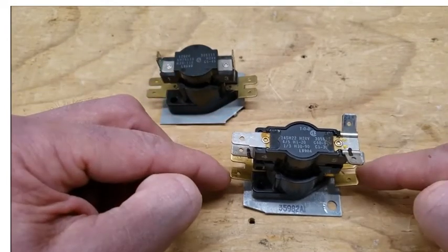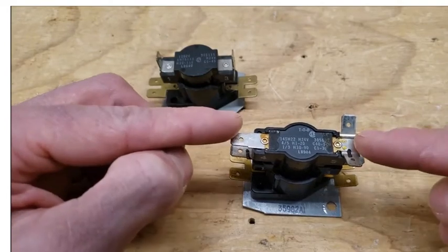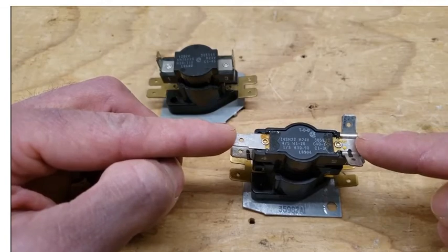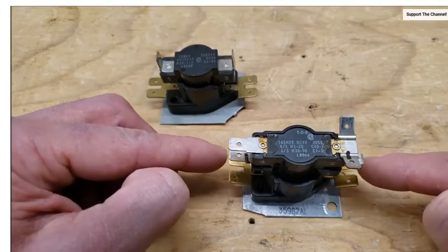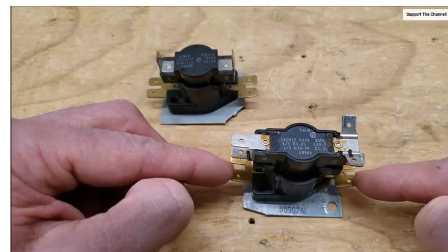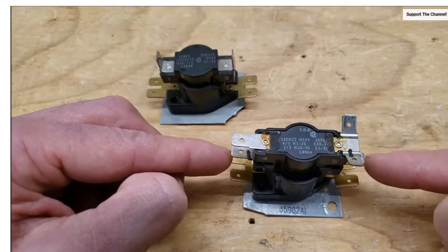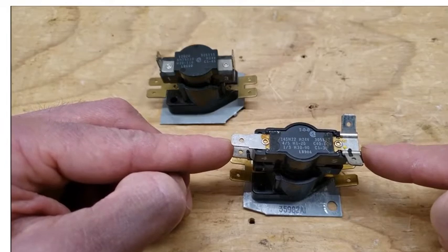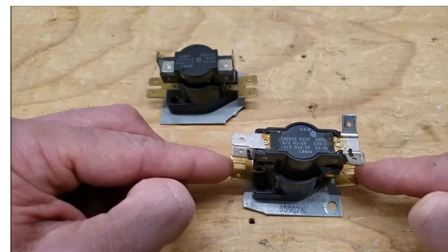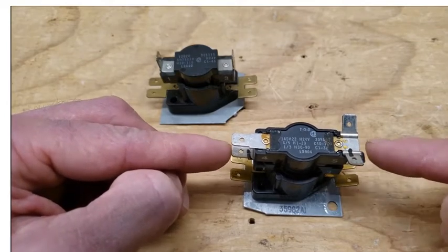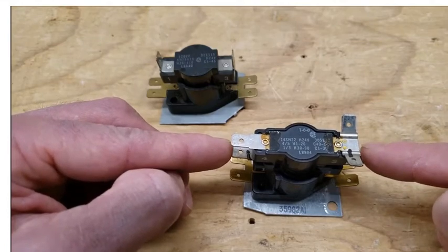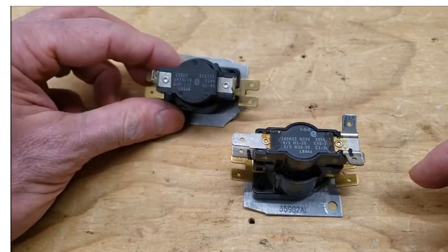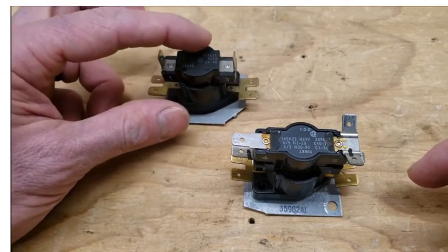After you disconnect the power down here, it's going to take 40 to 120 seconds for these contacts to open back up again. So just say you started at no power here and you're going to go ahead and power this. The second level of contacts is going to take 30 to 90 seconds for those contacts to close. And then when you take the power off the pan heater, it's going to only take 1 to 30 seconds for these contacts to open back up again. So this works just the same way. It just has 1 set of contacts with 1 set of time requirements.